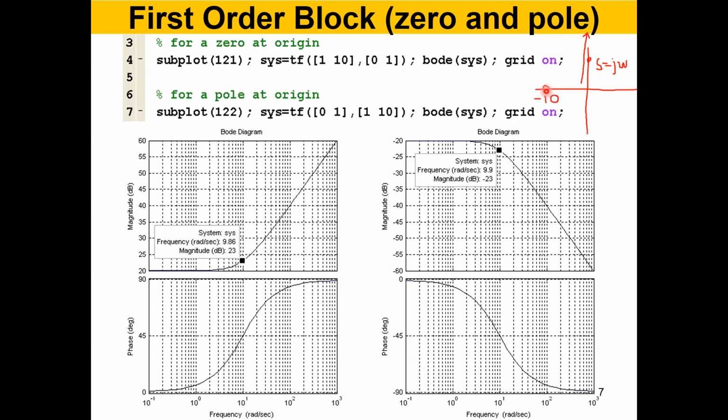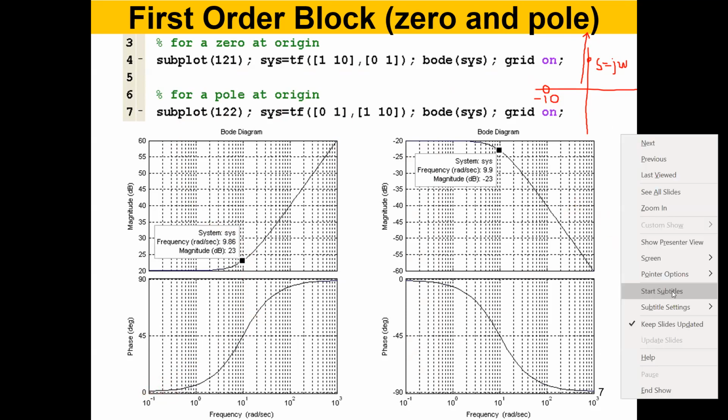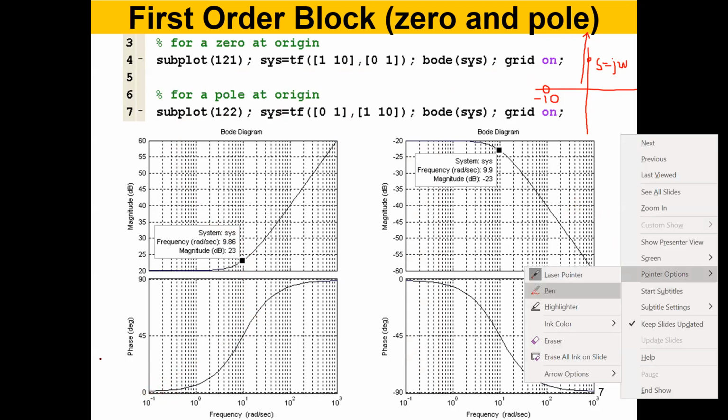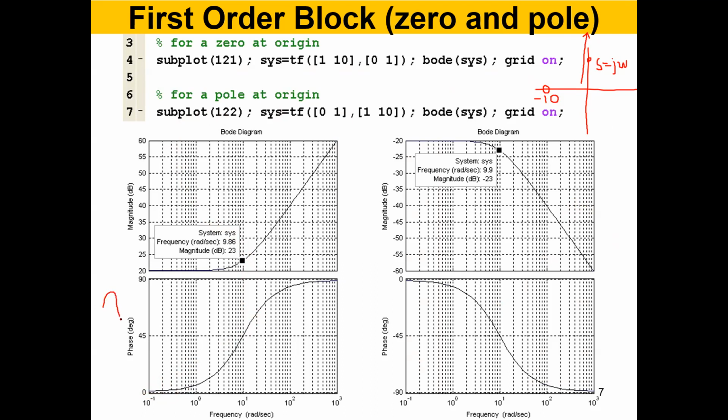And at the same time, what does it do for the phase rather, right? It starts with 0 phase, which means input and the response have 0 phase difference. What does it mean? It means if the input is like this, output is also like this. In phase, there is no phase difference. There's no phase lag.